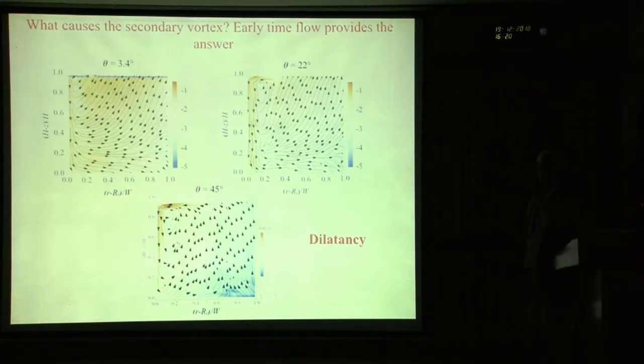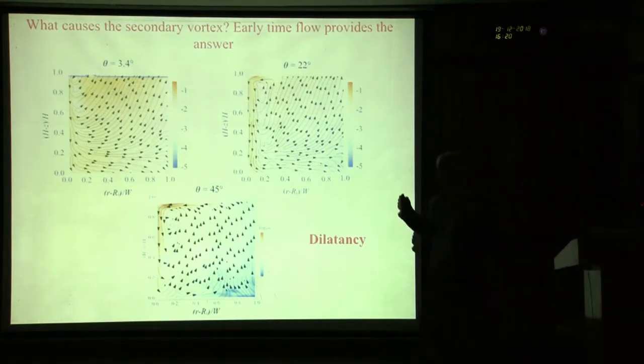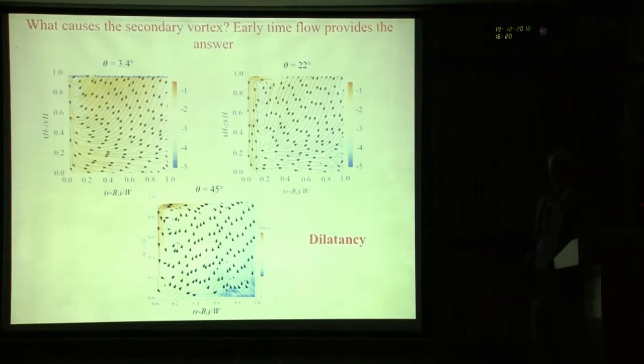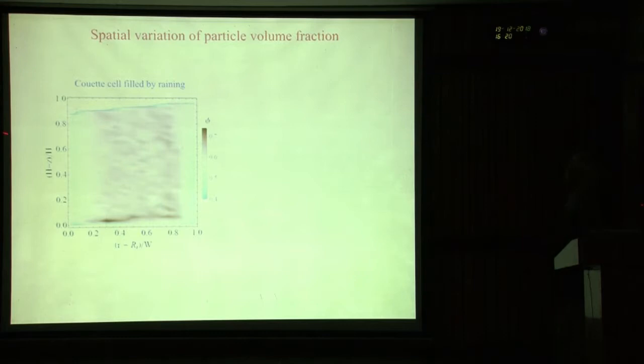And that's the reason I kept going on about theories having to capture constant pressure dilatancy. Constant pressure because initially the pressure at any given depth does not depend on radius or the radial position. Okay? So at constant pressure you can get a variation in the density. So yes, you can have dilatancy at constant pressure.